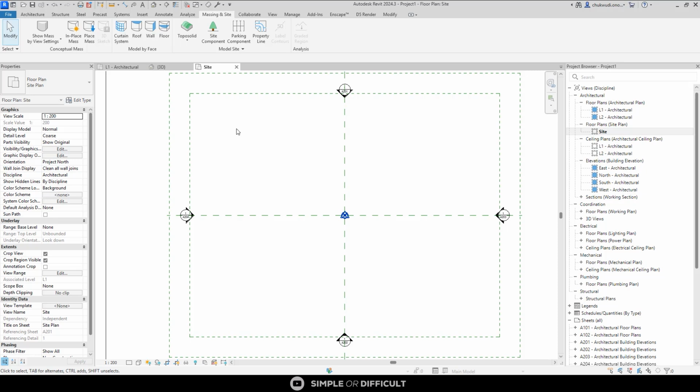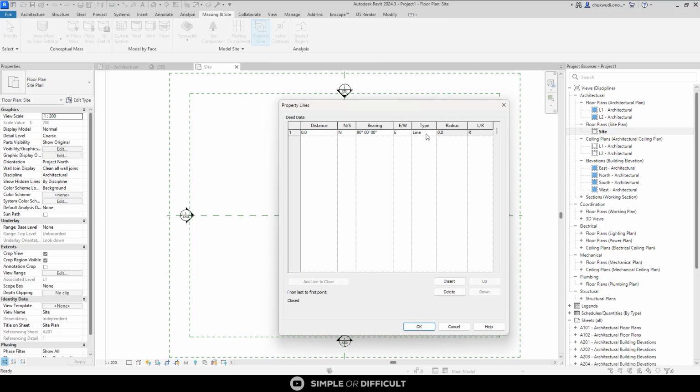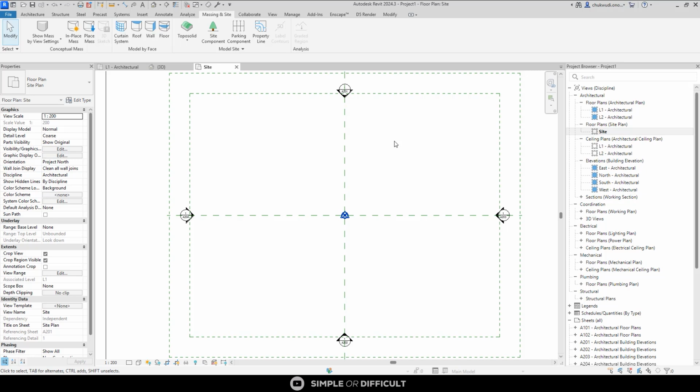Right. So before I hit this project line, when I hit it like this, you're going to see it's going to divide this into north, south, and east to west. All this will now require the normal survey plan that the surveyors give us. It is going to require us to start solving bearing. I, for one, don't like solving that bearing, but Revit has made it in such a way that you can actually input the exact stuff that the surveyor gave you. Right, so I'm going to show you how to set it to be able to do that.